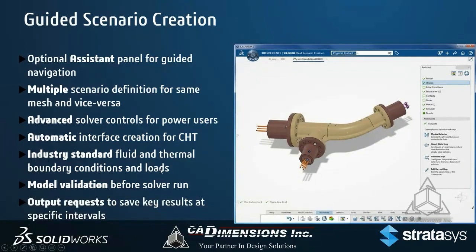And then rather than goals in desktop flow simulation, right, the output requests are kind of the same thing. With desktop flow, we always recommend setting a goal for whatever you want to measure from the simulation, whether it be pressure drop or temperatures of specific components or flow rates, whatever it might be. The platform solution, we have output requests to do the exact same thing.